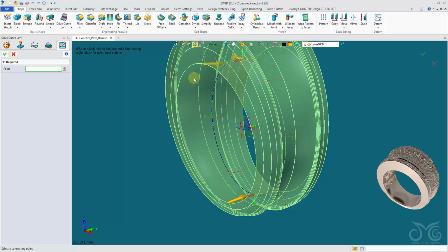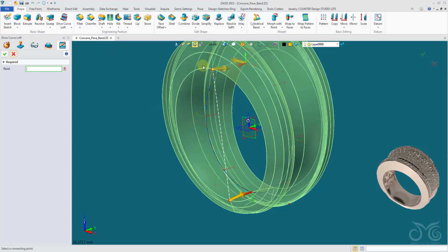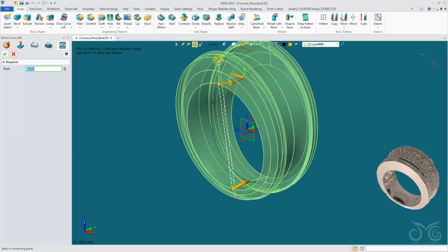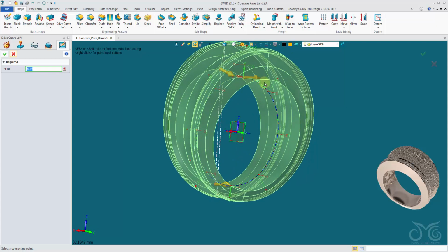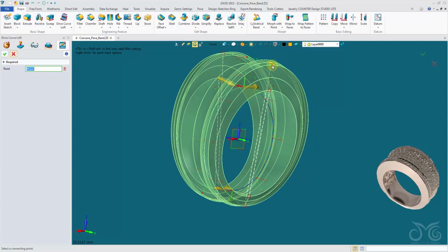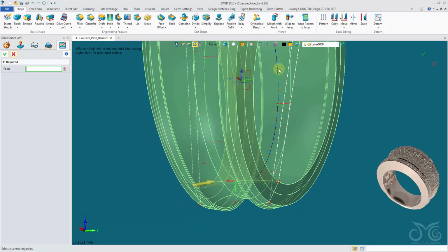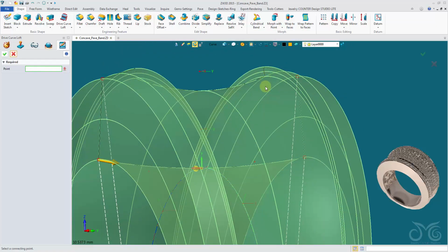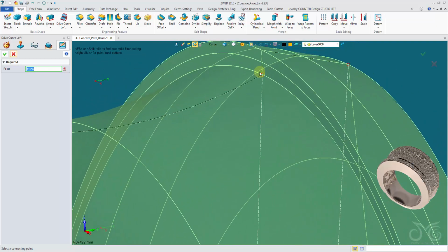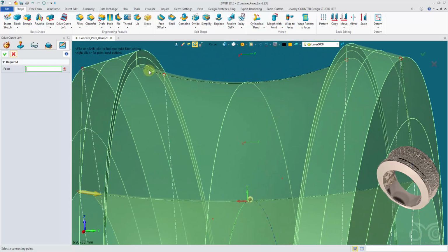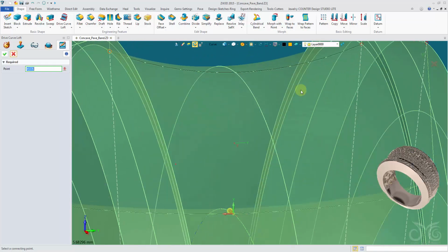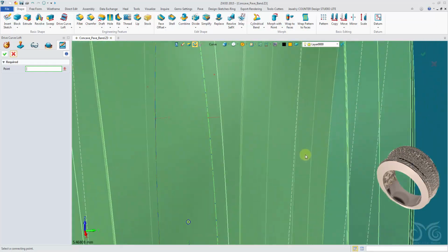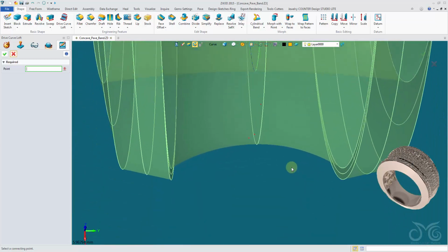So let's start off with the main connection lines. Let's do the 4 corners to the 4 corners. Okay, these are all coming in correctly. The issue I believe will be with our corner inside here. Left click to place one here, left click on the opposite side. Let's see where they're linked up to. Coming down to the bottom sketch.